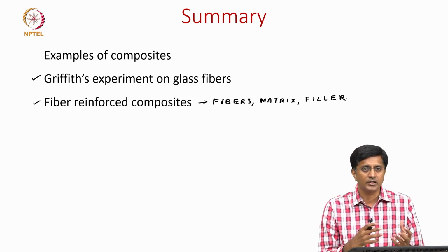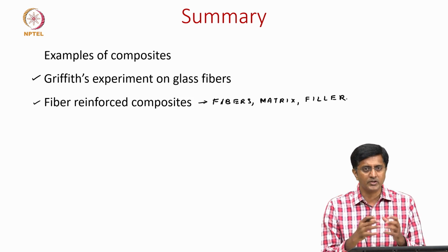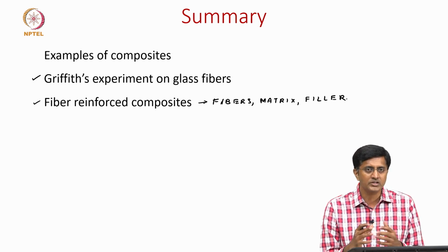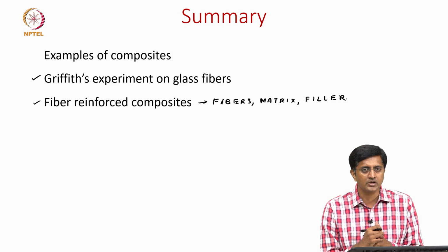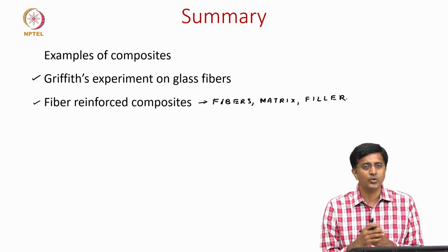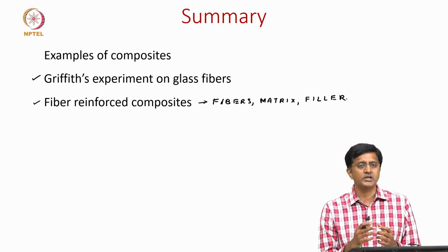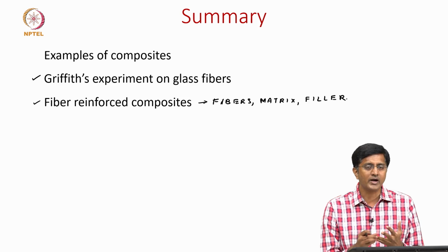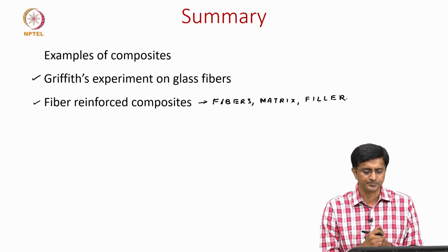The fibers give the high strength and stiffness, but the matrix material you use to bring these fibers together or to transfer or distribute the loads. Finally, filler is not for the structural enhancement of these composites, but to give other important properties such as low weight, resistance to fire or resistance to sunlight exposure, which is UV exposure.